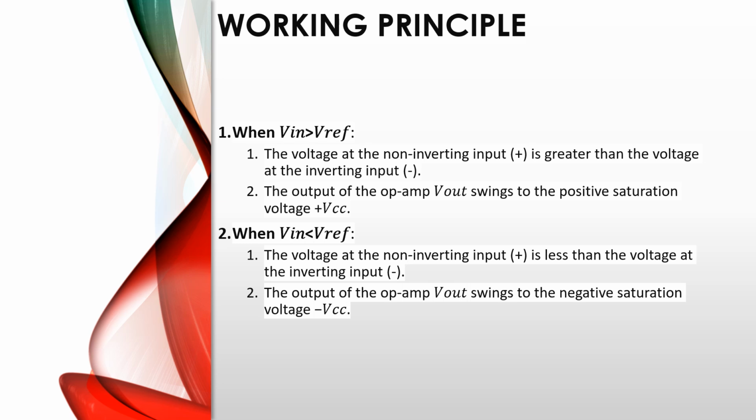One is V in greater than V reference, that means the non-inverting input voltage is greater than the inverting input voltage, and then V out swings to the positive saturation voltage and it gives positive VCC.